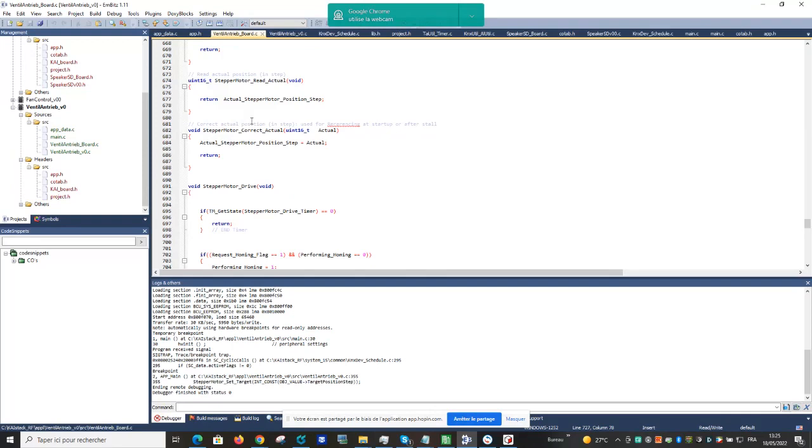Once we know we can drive the motor, we can use the temperature, we can charge the battery, once we know that the hardware is working fine, then we can validate the PCB, and we can already order and put these PCBs in manufacturing after having done some EMC tests. The application with all the details for software, we can do in parallel to manufacturing in order to be faster for time to market.